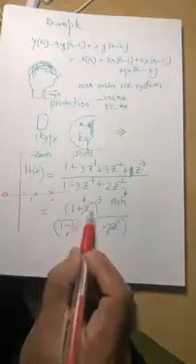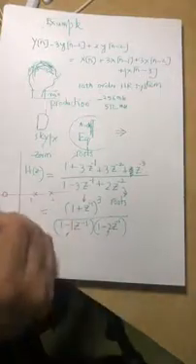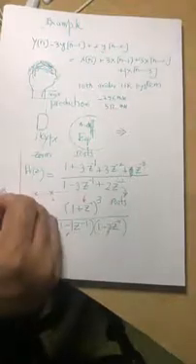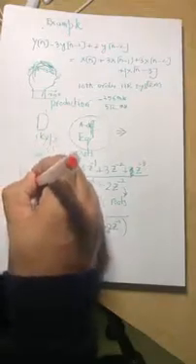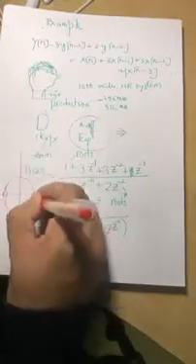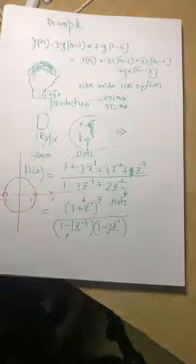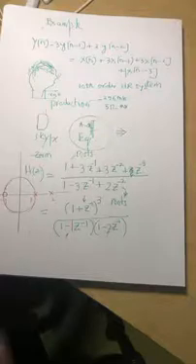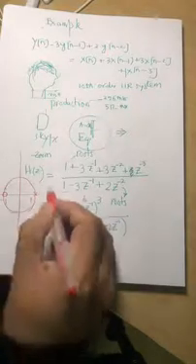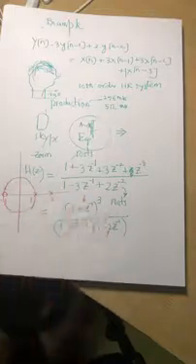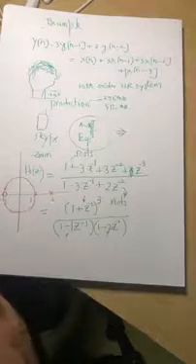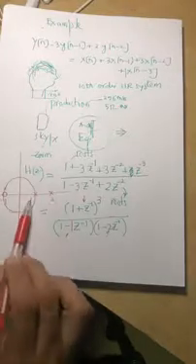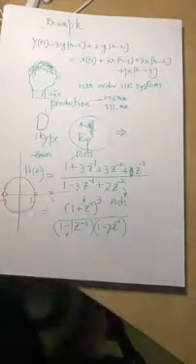Remember, it is 1 minus a z inverse, that's why it's a plus sign. So we say at minus 1 there are 3 zeros. And draw the unit circle, this is your drawing. And now you know whether it is a right hand side sequence. So we know the region of convergence is outside 2. If it is a left hand side sequence, region of convergence is inside 1. If it is a two-sided sequence, region of convergence is between 1 and 2. So in all these three cases,